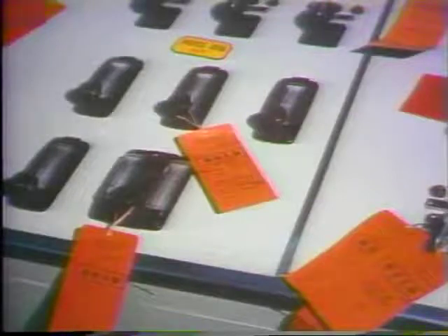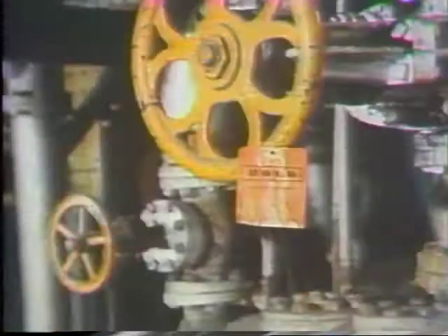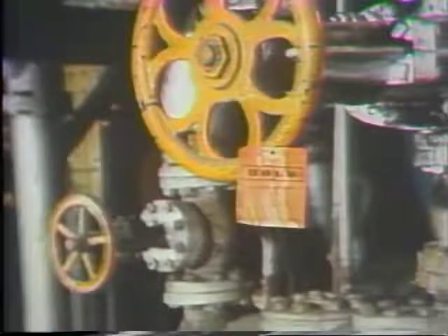Basically, when a system is tagged out, the operator places a color-coded tag on the components that isolate the equipment which is to be worked on. That is, tags are put on all components that could create a hazard if they were operated while the maintenance crew is at work. A piece of equipment that is tagged for personal protection should never be operated until the tag has been removed according to plant procedures. What safety really boils down to is remaining alert to anything that could cause harm to yourself or others. If you ever have a question as to the proper procedure to follow, consult your plant's safety manual or ask your supervisor.